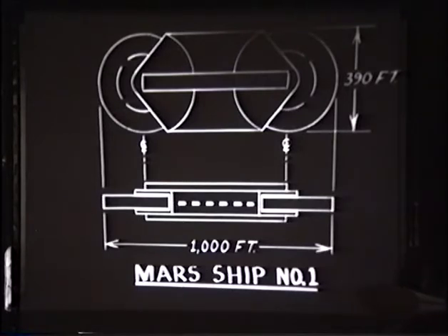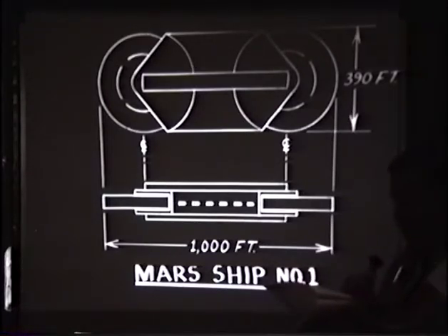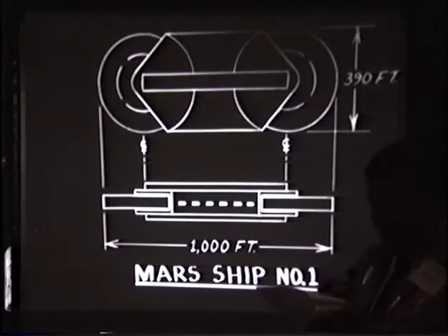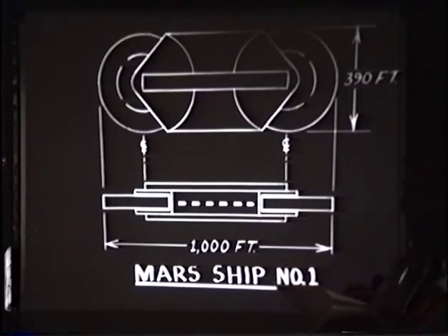Consumable atmosphere is 7,300 FPS pounds of oxygen, 9,586 FPS pounds of nitrogen. Mission capacity is 3,650 man days at 2 FPS pounds O2 per day per person without recycling, or a year's capacity for 10 persons. Drinking water, 18,250 US gallons, or 146,380 FPS pounds of water. 3,650 man days at 5 US gallons water per day per person without recycling.